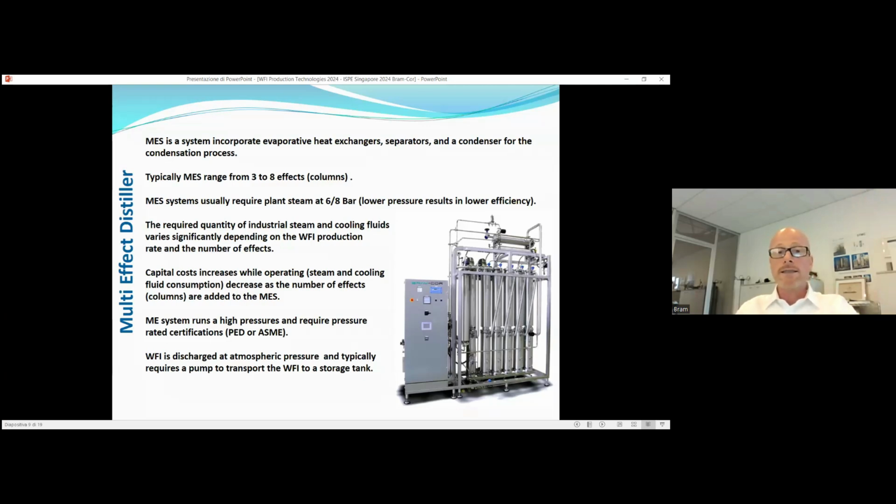It's a system that incorporates evaporative heat exchangers, a separator, and a condenser for the condensation process. Typically it is called multi-effect distiller or multi-column distiller because it operates in a range of 3 to 8 columns. There is also the possibility of the single effect distiller, that is a single column, as the name says. Typically, depending on the capacity, it is from 3 for small capacity up to 8 for large capacities.